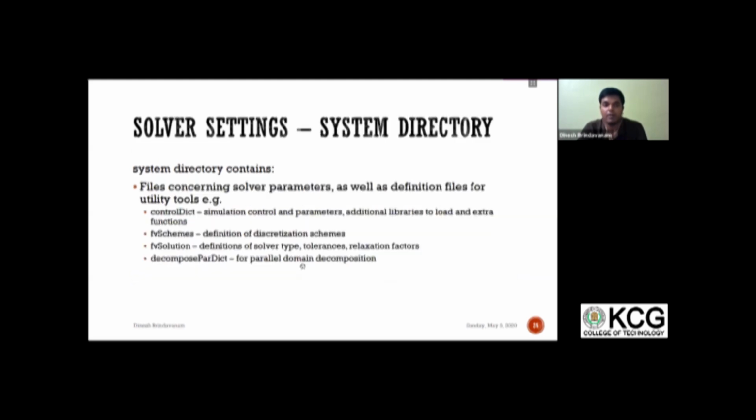So this one corresponds directly. Dimension 2 means meter square per second. So what does it specify? It specifies the kinematic viscosity. You need to use this to know that. Once you're stuck with some script and you don't know what it is for, you can find the dimensions of that one, convert it, and find the unit and the property which you are trying to find from that particular script.